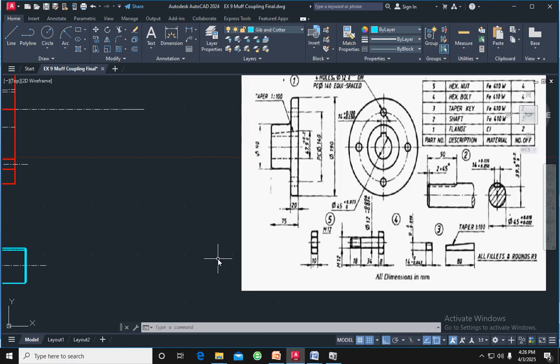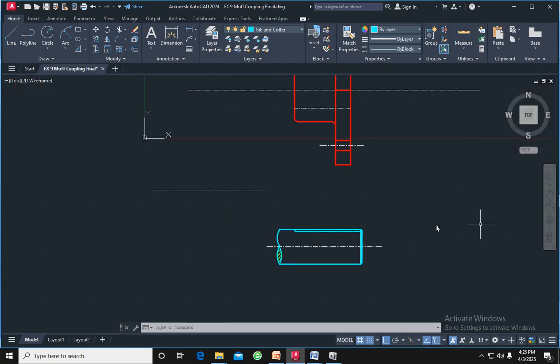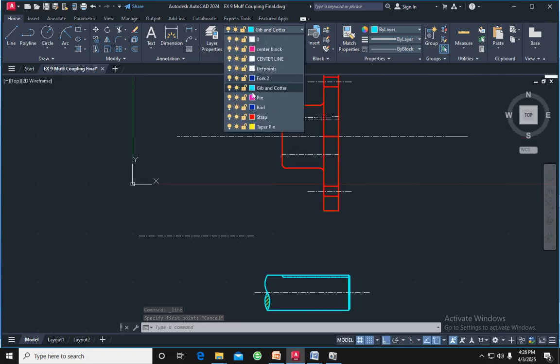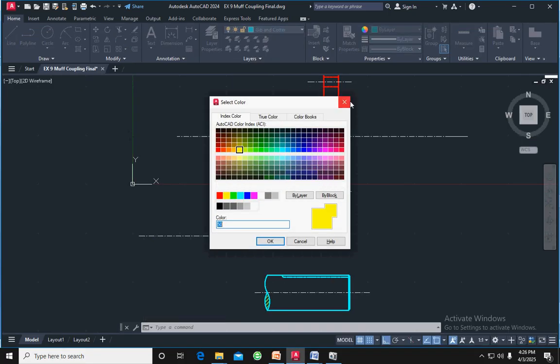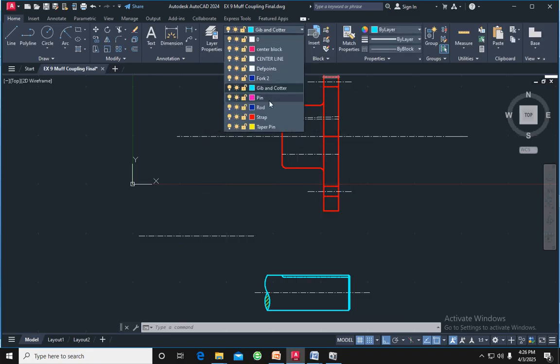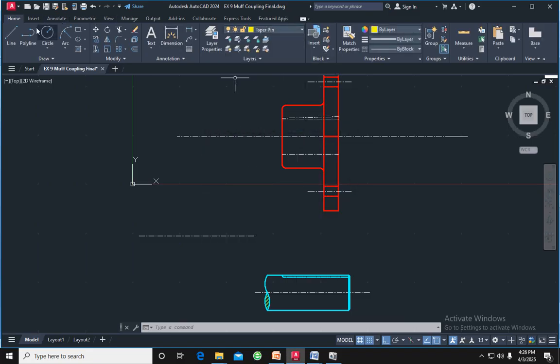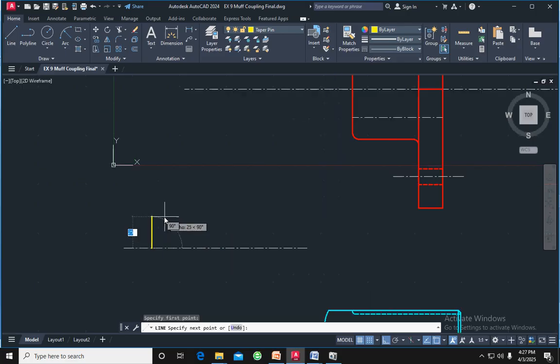60 length, 34. Okay, we have to draw a line. In this case we have to change the dimension. We have to draw a layer. For the layer we select this layer. We have to draw the line, click the point and click here. The diameter of the bolt is 12 so the radius is 6.